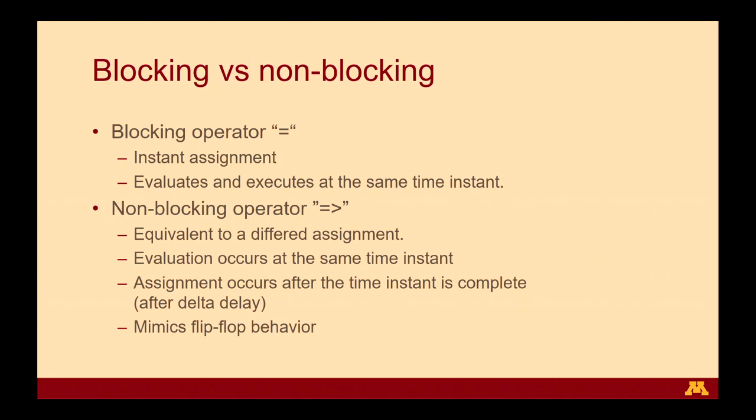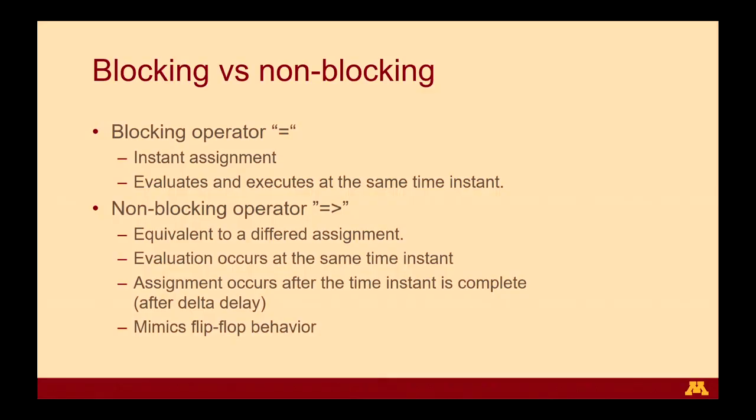Whereas the non-blocking statement is more designed to how flip-flops operate. As you know, in a flip-flop there's a certain delay between when the clock edge comes and when the Q pin of the flip-flop toggles. Because of this delay, if there is a cascade of flip-flops, the data will not be captured on the same edge as which it was driven, and is always captured on the subsequent edge. That is how delays are modeled within Verilog and SystemVerilog, and in this particular case, the non-blocking operator tries to mimic that behavior.